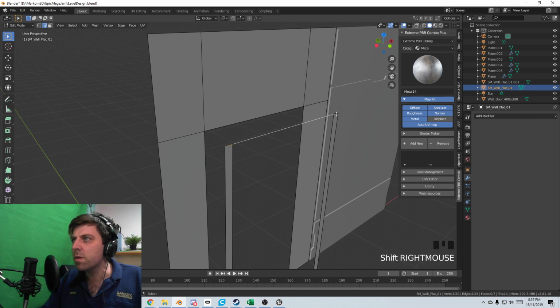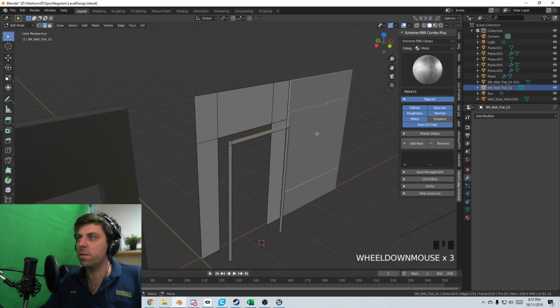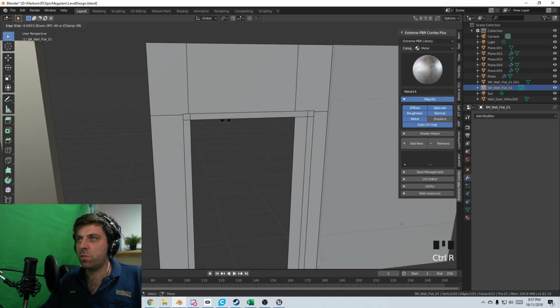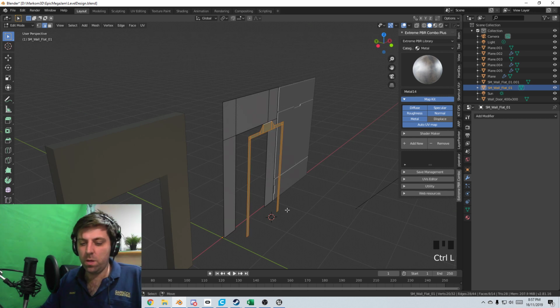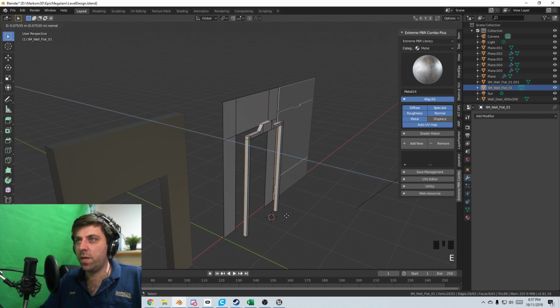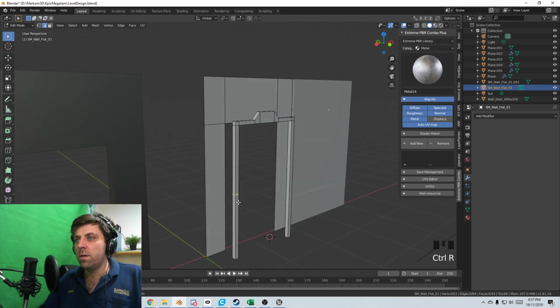These three, E to extrude Z. And we'll do my age-old trick. Control B, put in those edge loops. Control B. Nope, too much. Control B. GZ. Beautiful. E to extrude, and we'll plop that out a little bit. Delete faces. Let's do the same on these. I just love doing these little insets.